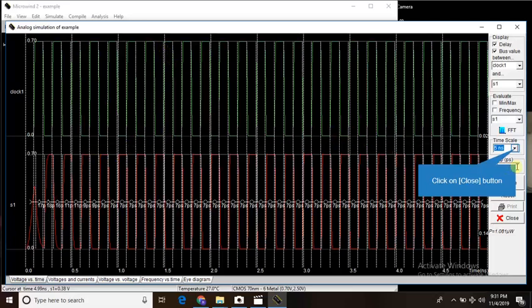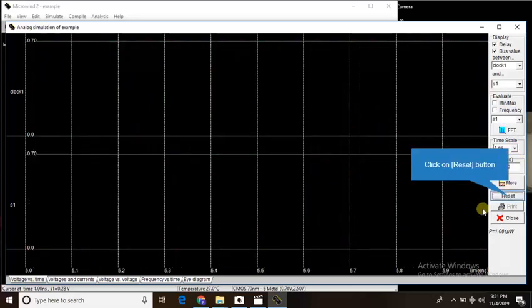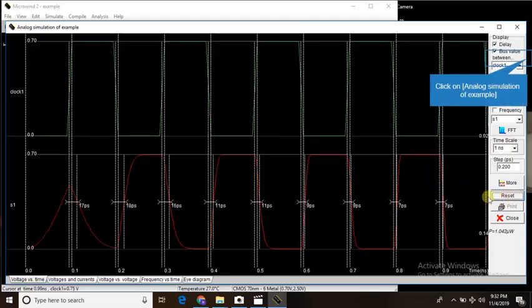So it has simulated. Okay, so let us reduce the time here. It is up to 6 nanoseconds. Let us make it up to 1 nanosecond. Initially it is getting charged. Now you can see that this is the input. When input is going low, output is going high, and when input is going high, output is going low. There is a time delay coming up there. How much is the rise delay and fall delay? They are mentioned here in terms of picoseconds.